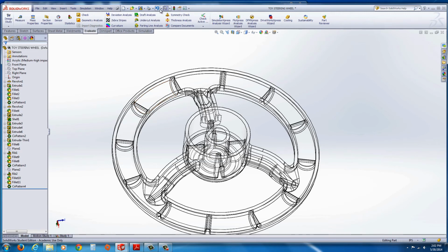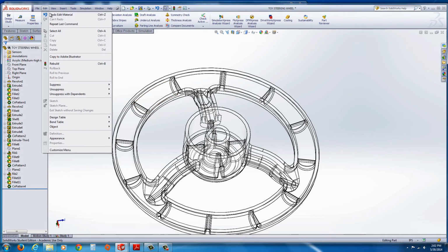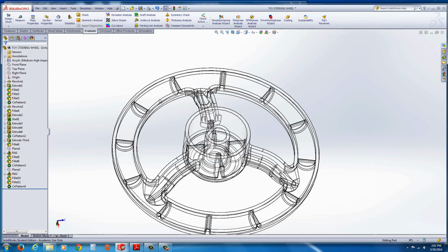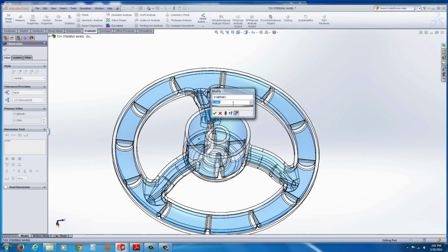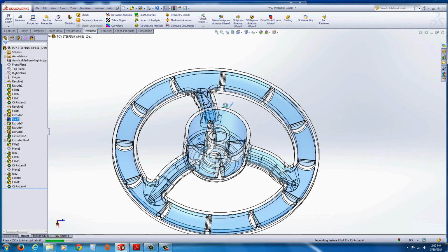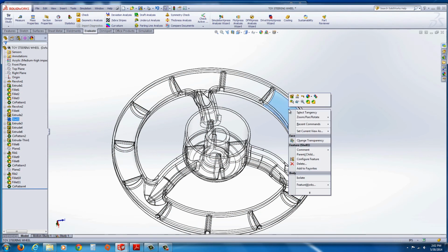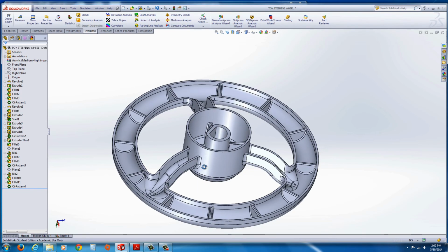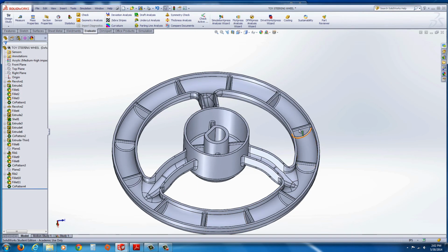So if we go back and we're going to redo, I can't redo it, so I'm going to just go ahead and double click on the surface, find that 0.1. We'll change it to 0.06 and rebuild. So we thin that out. Let's get rid of that transparency there. Okay, also some of these aren't really necessary in every single position.